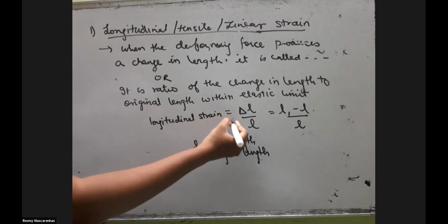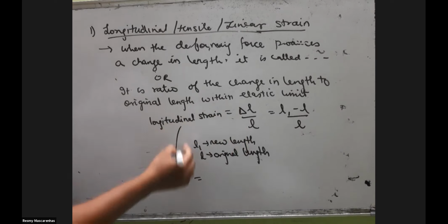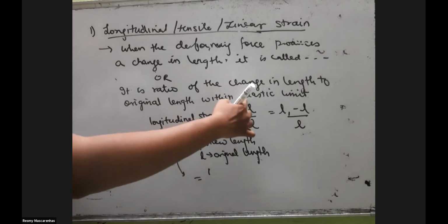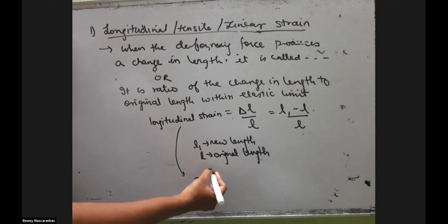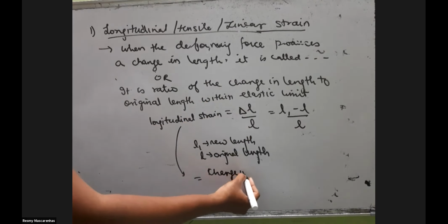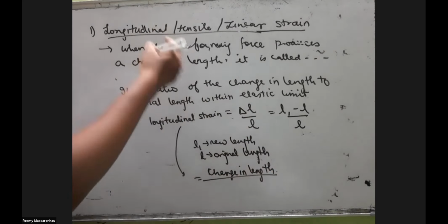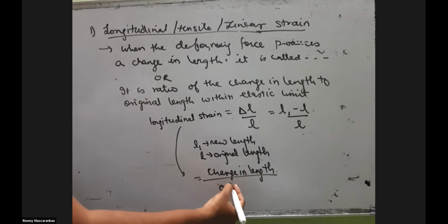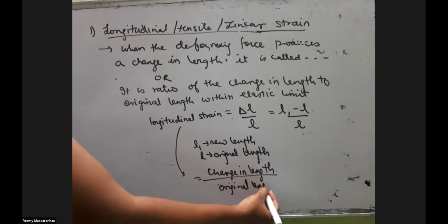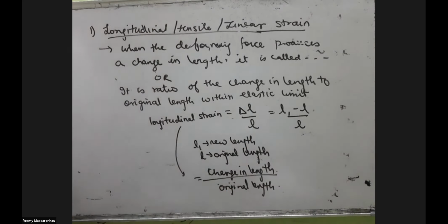So it's nothing but change in length. I did not write in terms of definition. You can write change in length. Same it is. Instead of dimension, you have to just use the word length. Longitudinal strain is change in length upon original length. Same thing. Now it's simple.